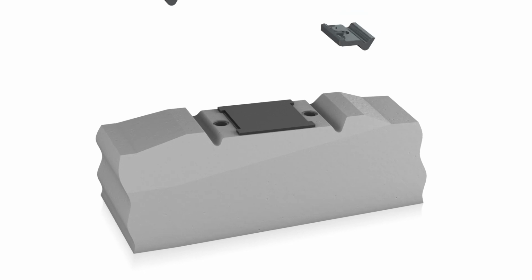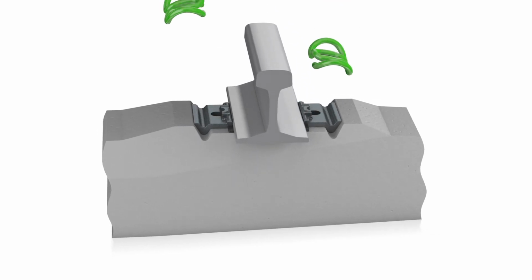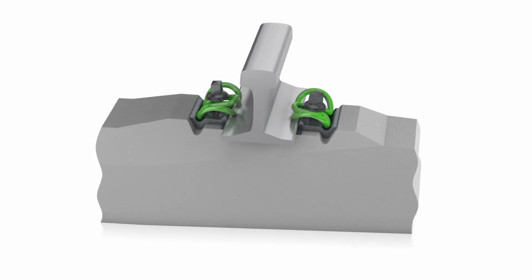Angle guide plates hold the base of the rail and the rail pad in place. They prevent shearing and tilting and keep the track gauge of the rail. Screw and tension clips ensure the vertical stability while allowing for elasticity, thus reducing wear and the need for maintenance. This type of fastening is called a W-track superstructure, as it vaguely resembles a W.